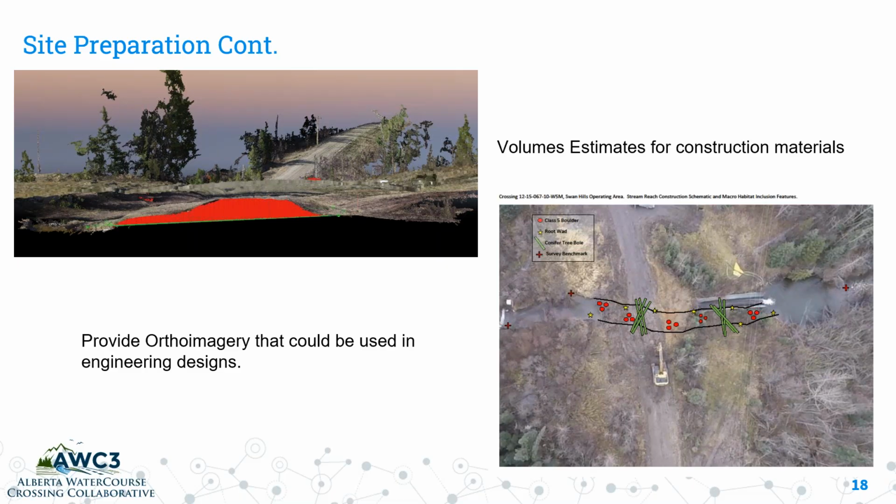So you could actually look at the amount of volume that I'm going to have to excavate to get this culvert out. And that can help you in getting a better estimate of your timelines. So you could say, okay, I know I have X amount of cubic meters that I need to move. My excavator can do so many cubic meters per day. And I have a lot better idea of what the timeline would be for my excavator to do that.